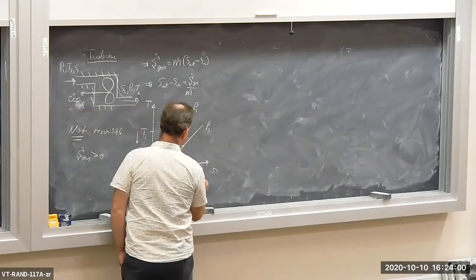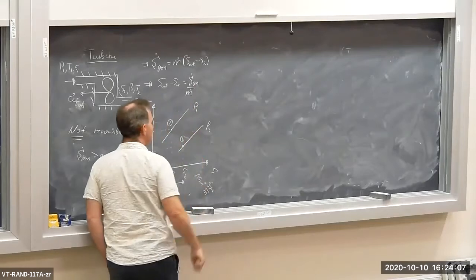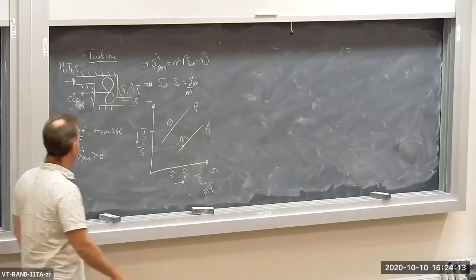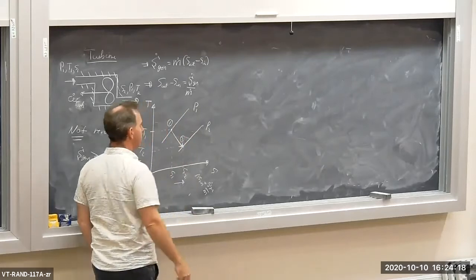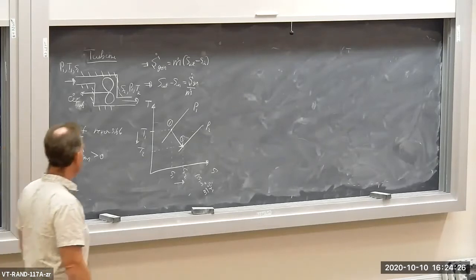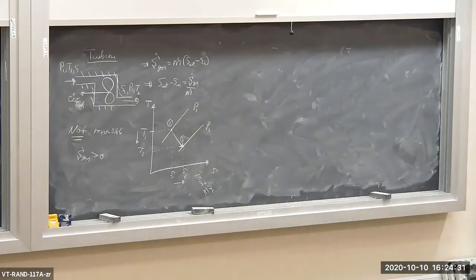So this delta S from the inlet to the outlet is S dot gen divided by m dot for the working fluid. So the process looks something like this, for the air as it flows from the inlet to the outlet of my turbine. Okay? So that's what the process looks like for the non-reversible adiabatic turbine. Delta S is positive as we go from the inlet to the outlet because of entropy generation.